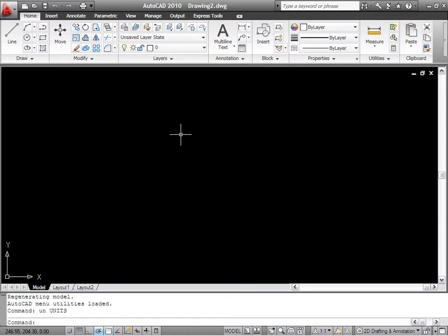To show that you are typing something, you can turn on this icon here called dynamic input. Once you turn on, and when you type anything in the space, it will show you in the screen that there is this input. I'm typing in L for line. If I confirm this is the command that I want, I can just press spacebar to continue.